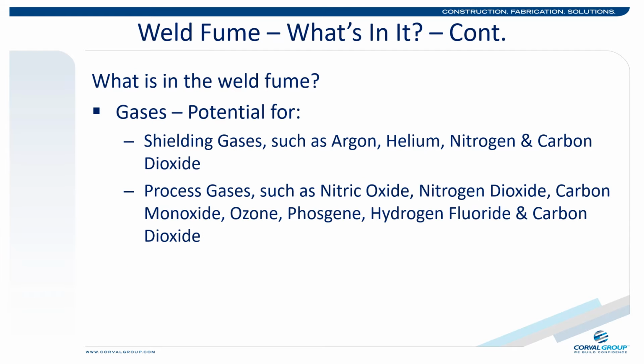In addition to the metals contained in the fumes, there are gases as well. Shielding gases are components of some types of welding activities and materials. As the name suggests, the shielding gas shields the solidifying molten weld from oxygenation, as well as impurities and moisture in the air, which may weaken the corrosion tolerance of the weld, generate porous results, and weaken the durability of the weld by changing the geometrical features of the joint.